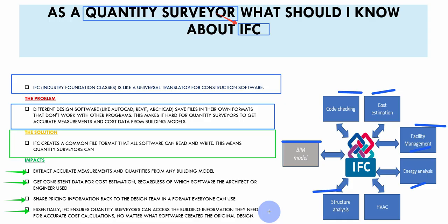You may not have Revit, Archicad or ProtaStructure software, but you remember, you've already installed BIM Vision. So then there is no problem, just talk to your designer. They convert their model into an IFC file, then send it to you. Then you are able to read it and extract the quantities, as we are going to see in our next session.